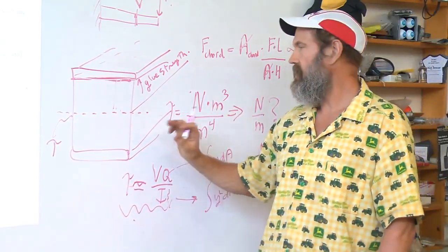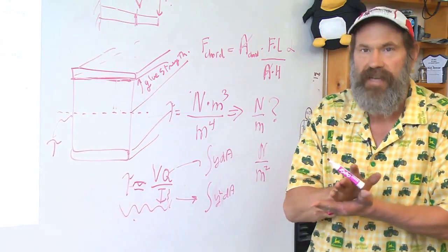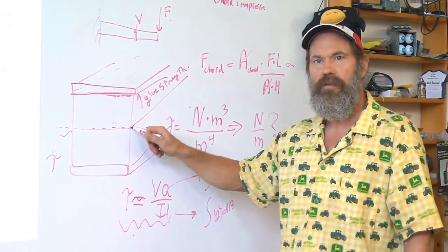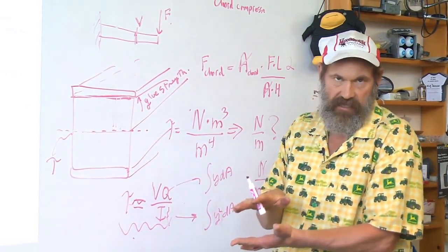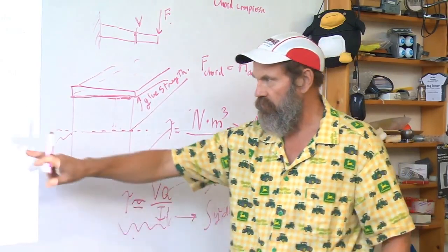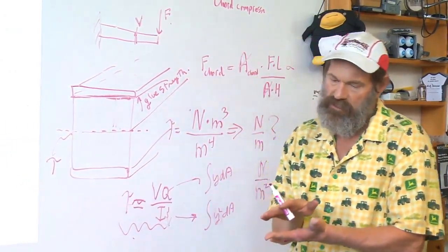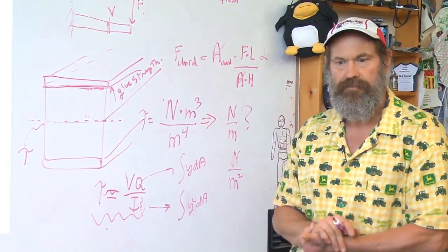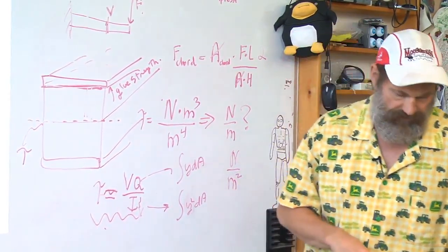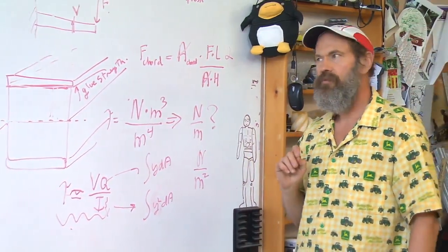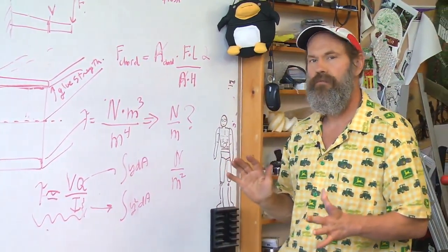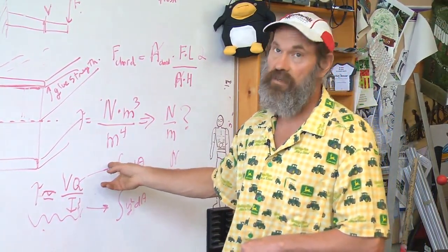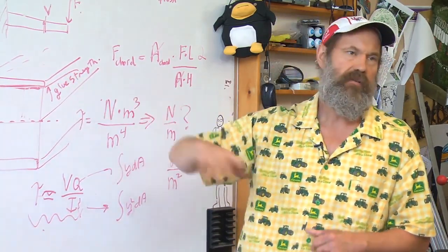So you use the ability to calculate the shear stress in a laminate to make sure that if you have a soft core like foam, the soft core, which is nice and lightweight, itself doesn't just shear through the middle. And you also have to check the shear stress in the glue layers to make sure the glue won't let go. Very simple to do, very fast to do. And this should have piqued your interest in, wow, I'd like to be able to design composites to really do good. And it turns out there's a spreadsheet that goes with the course too.